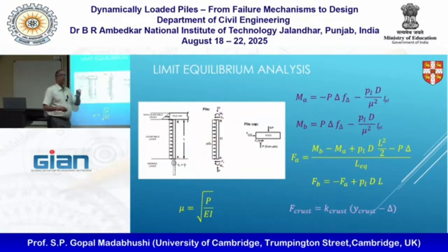These layers are always going to be of fairly limited thickness, maybe 1 to 2 meters. So although I am applying passive pressure, that triangle is going to be fairly small. In the simplest of cases, we can say the liquefiable soil, as it is trying to go towards the pile, is applying some kind of uniform pressure.